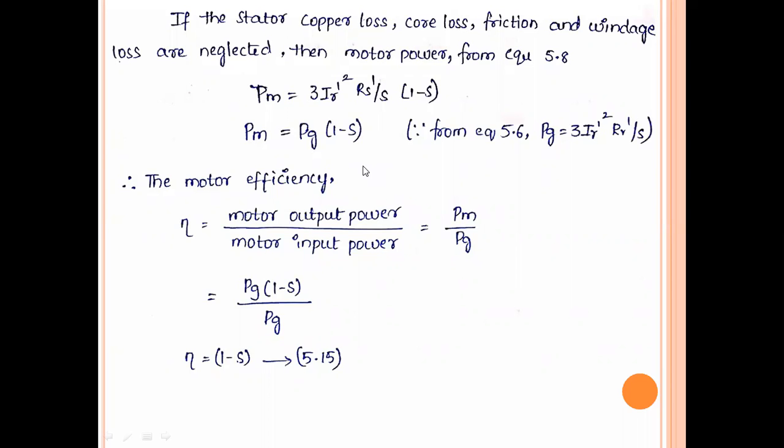That leads to overheating of the rotor. If the rotor loss is increasing, the resistance will convert its energy into heat, so the rotor will be overheated. So finally, speed control of an induction motor with stator voltage control produces a reduced efficiency.